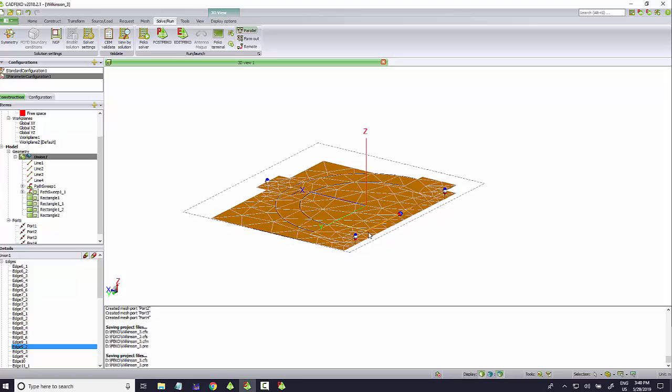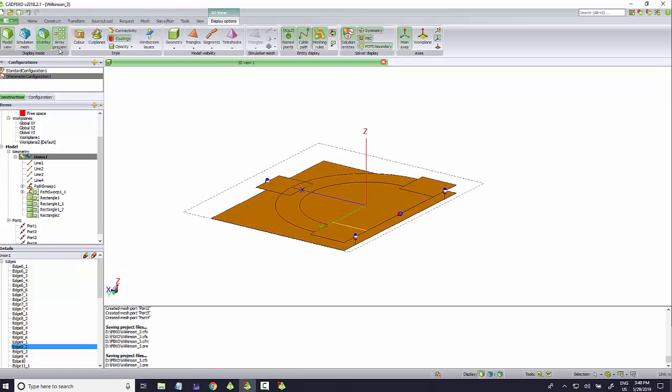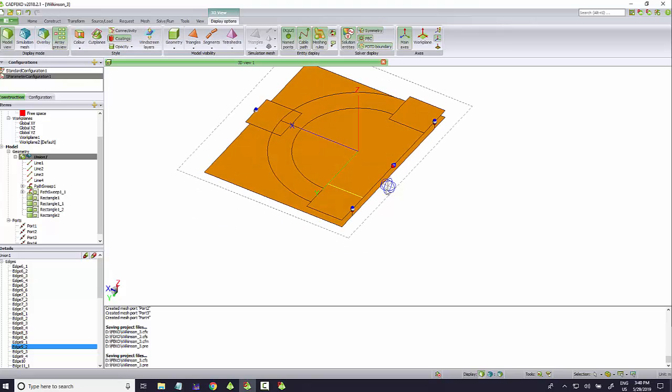The second thing, one of the possible reasons for that, I'm just going to display, turning off the overlay. Probably this connection here of the resistor, 100 ohm resistor, is too long. It's probably creating some inductance or parasitics on this structure, so we should work on the layout to make this connection not as electrically long as it is right now. That should be another option to improve our design.